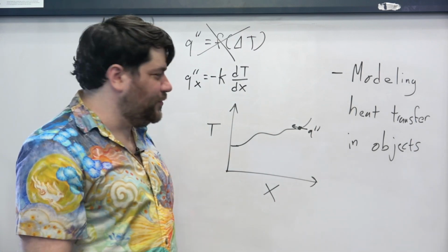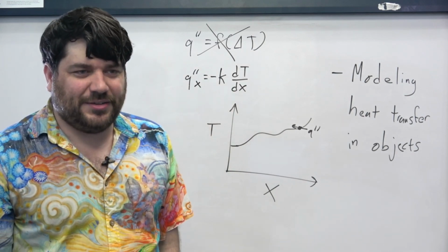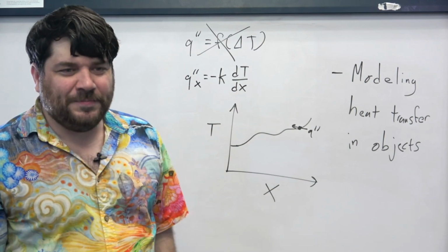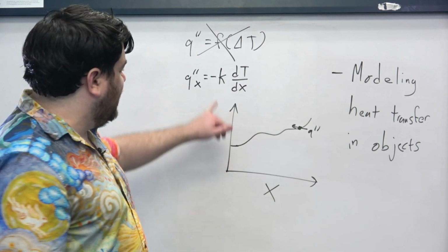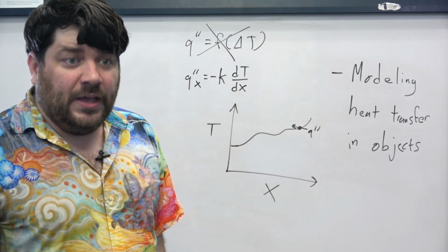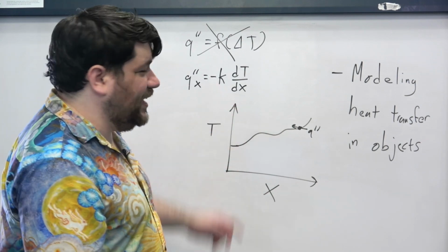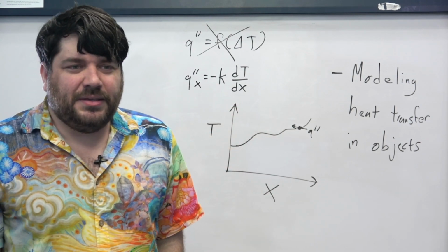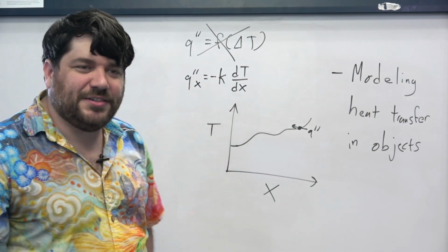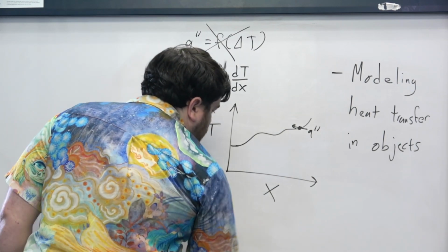Heat is transferred from hot things to cold things, the heat transfer will always oppose the direction of dT/dx. And you can do this argument in your head if you imagine that the curve was decreasing at this point, and you'd find the exact same thing, right? So we have to attach this negative sign in order to be physically consistent, and in order to keep these k's positive. One thing that we could have done was just to make the k's negative, but it's easier to just keep the k's as being positive material properties and then just attach the minus sign on the outside, okay?